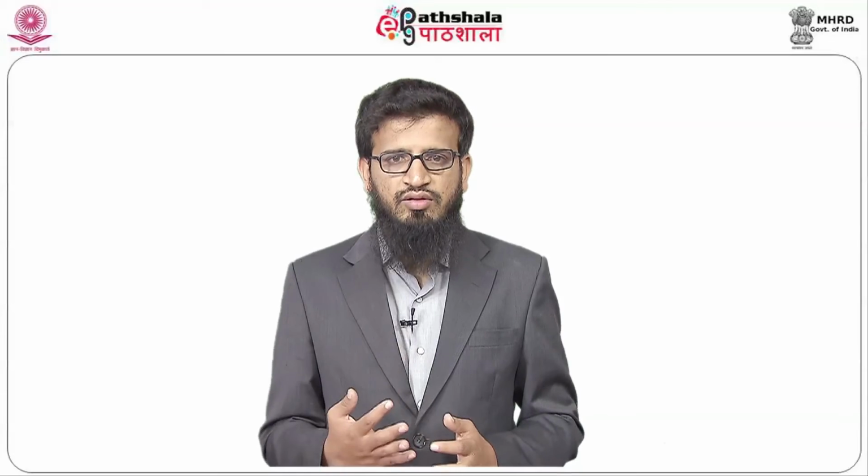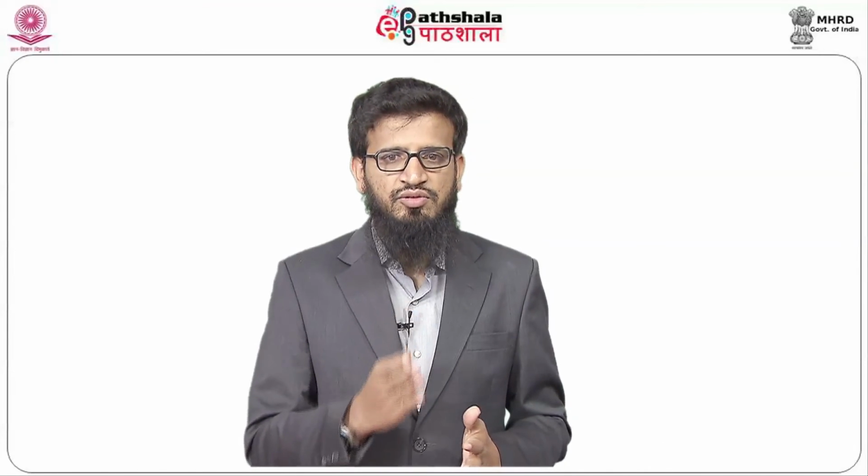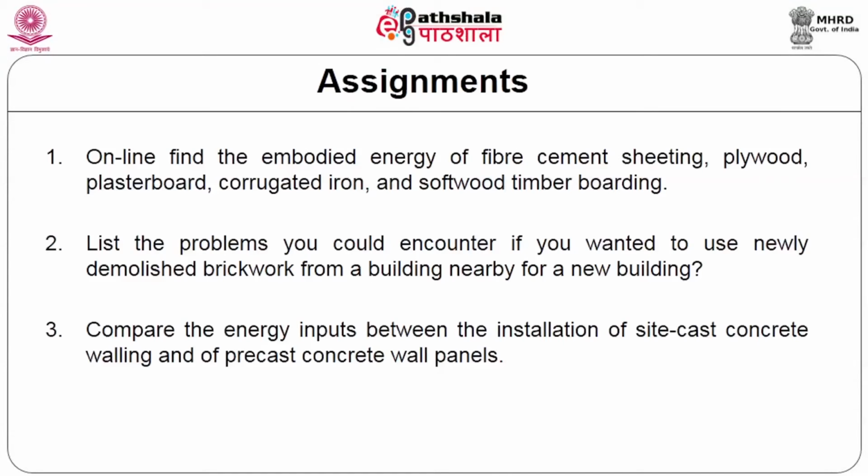Whenever you pick up any material, please ask them how it is procured. If it is procured from a green source like solar energy or wind, where the factory is using solar or wind, then use them, because they are created using renewables, which reduces the embodied energy in the manufacturing process. Use efficient building envelope, as I have explained in one of the previous slides, how a design A, B and C could make a difference. So, basically this is what the entire embodied energy is all about.